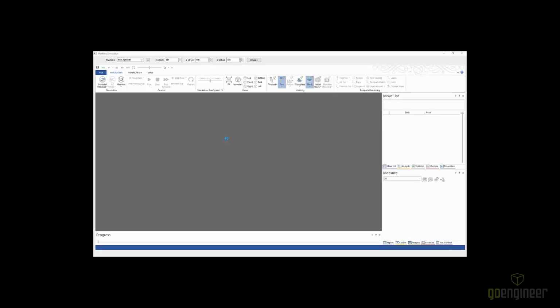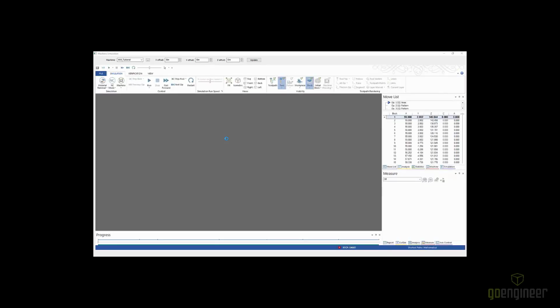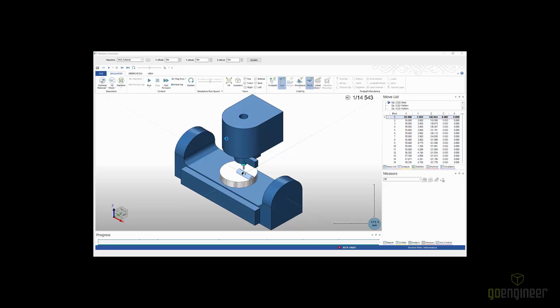This isn't the exact software, though it's very analogous, that I'm pulling up currently. What really separates it is we're including all parts of our machine. Everything's involved. And the other big benefit, really the crucial benefit, is when we're in software, our simulation there is just a tool following a line on the screen. Nothing too complicated. But in the virtual machine simulator, we're actually using the G code that we post. We're taking G code, posting it out, and using that to run the simulator.